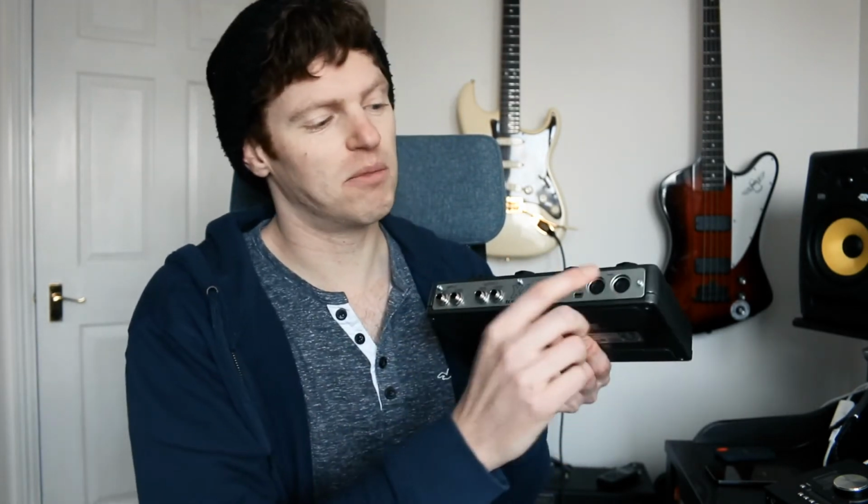So if I'm sending MIDI information into here, then I could send additional stuff like note information. Now because this is a loop pedal, it doesn't need to receive note information. This is more for MIDI clock in this situation. But let's say I want to chain something else after this, that's where MIDI through comes in. It's for chaining other instruments together.